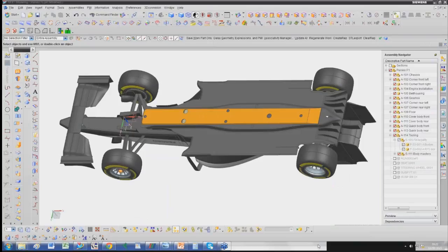It can be strong, and the core can be small with a lot of suction in the middle, or it can burst, and it's like breaking up and splashing. That will be at the end of its life, if you want. So the actual pressure that the vortex will apply on the tire when it hits it depends on the state of the vortex. If it's very strong, it won't necessarily reduce the pressure on the tire very much. If it bursts, then it will reduce the pressure. So we're talking something very difficult to adjust.